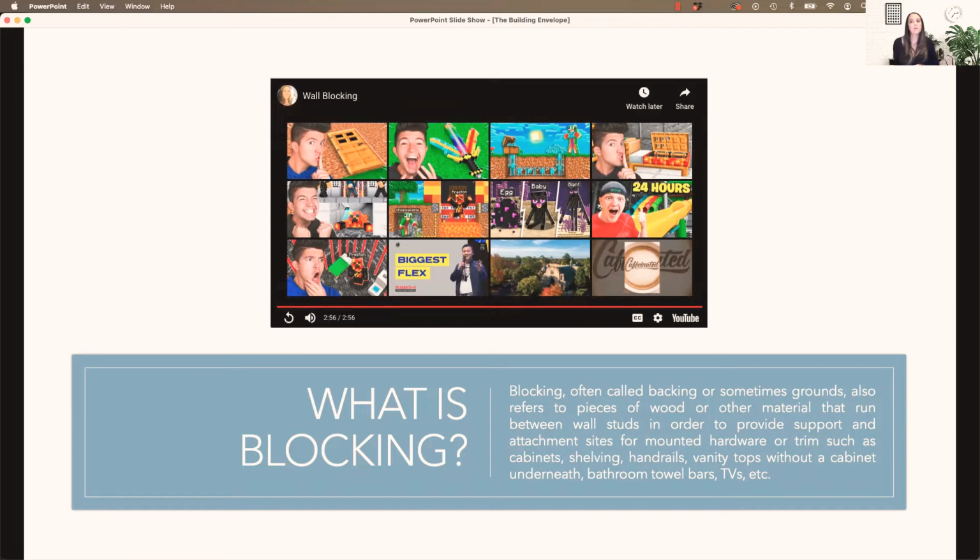When we talk in a few weeks about universal design and accessible design, a lot of times in newer construction we're seeing people planning ahead for aging in place. So you might specify in a bathroom design to have blocking available if grab bars need to be added at some time. It's really great if you have an opportunity to add blocking.